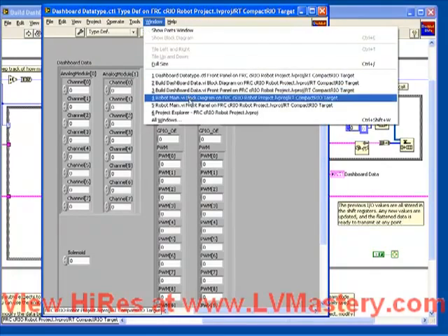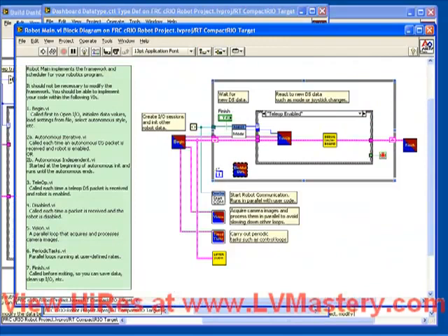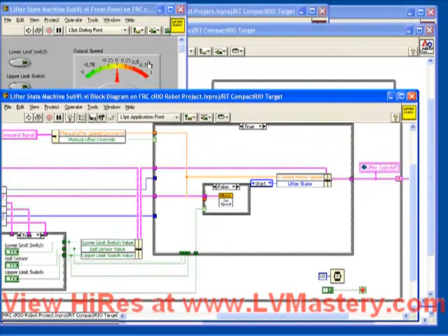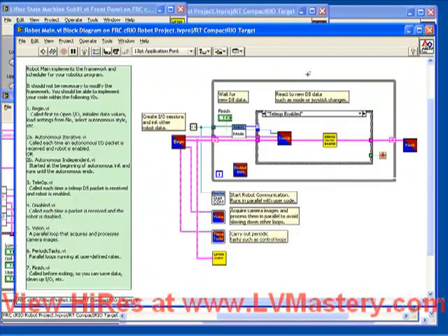So let's go back to robot main, then to our lifter sub-VI, and take a look at the block diagram. Remember that what we're outputting from this shift register is being put into the lifter typedef global. All that information is being placed in the global specifically so that we can take a look at it back at our robot main in our debug dashboard. So if we want that same capability in our driver station dashboard, why not make some of that same data available inside our dashboard typedef?